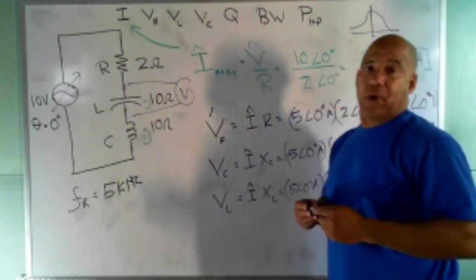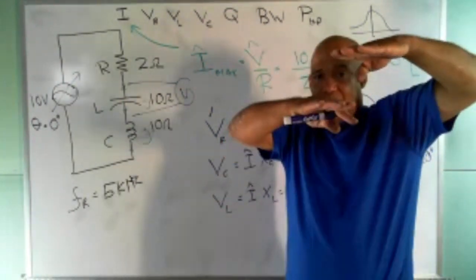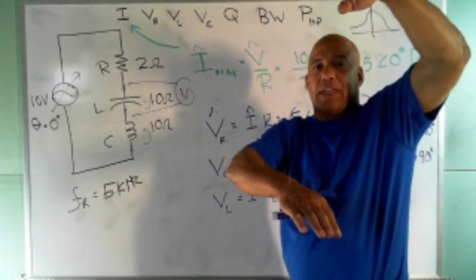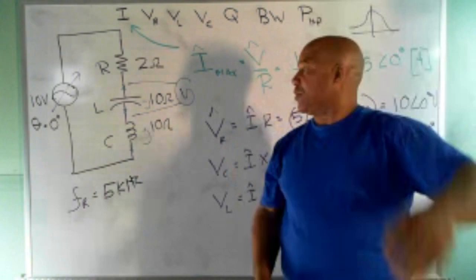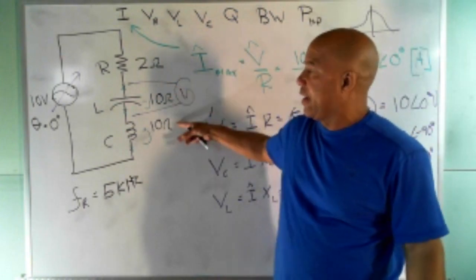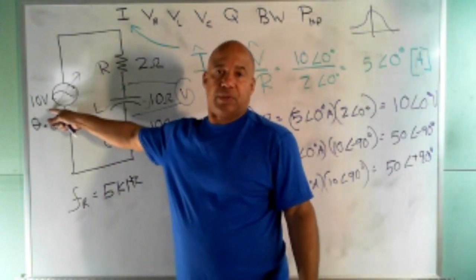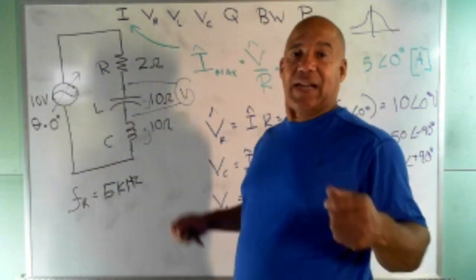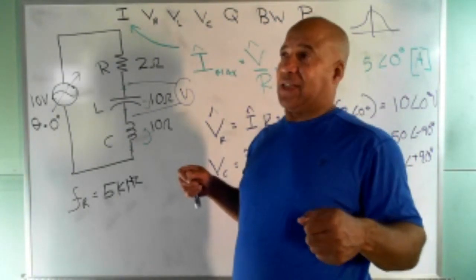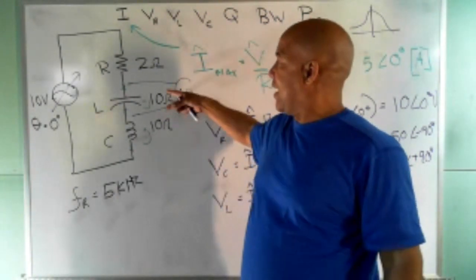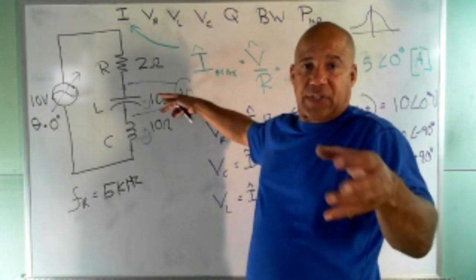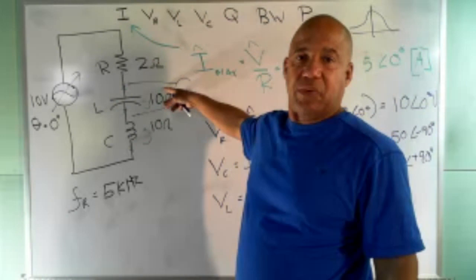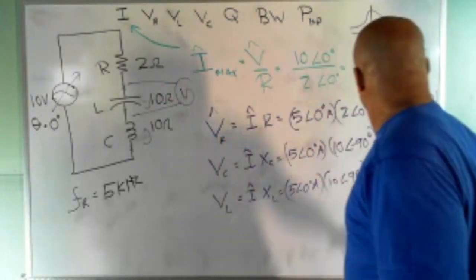What you would see is a sine wave, and the way you would know you're in resonance is the sine wave amplitude will get big. Resonance is the biggest it's going to be. If you go past resonance, it'll start to shrink again. So you got that amplitude across here and here, 5 times the source voltage. At resonance, my reactive components are highly sensitive. If you're using this to pick up radio frequency, at the frequency which you tune to the station, you'd have a very, very high voltage for that particular radio station frequency on your resonance circuit. 50 volts.